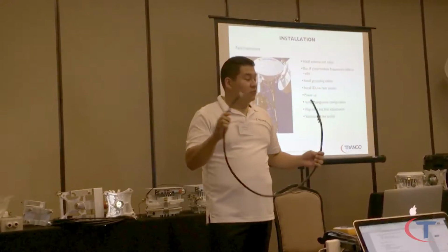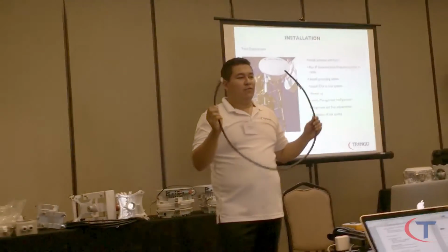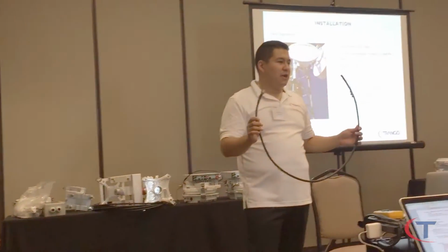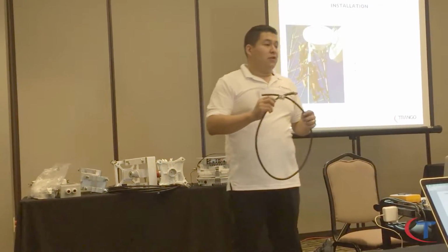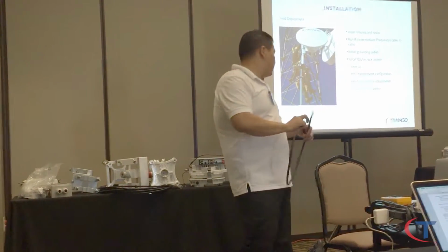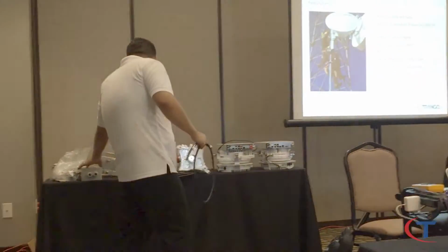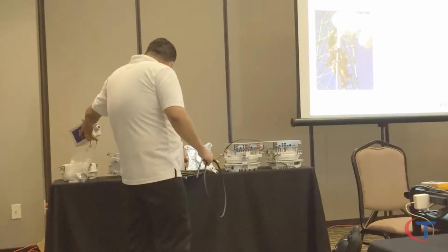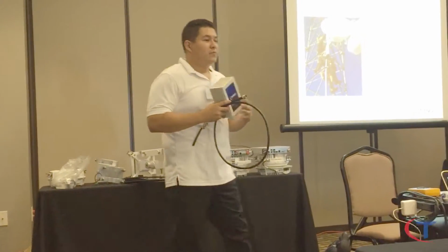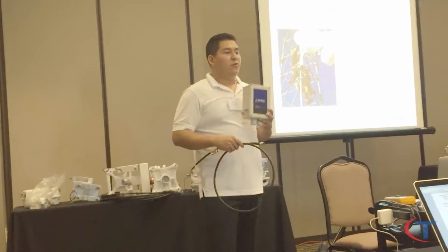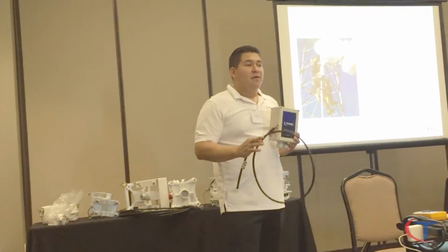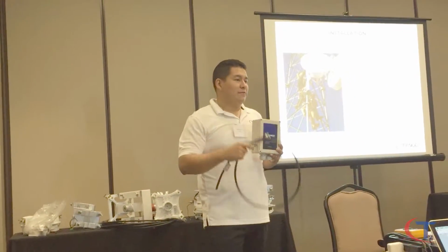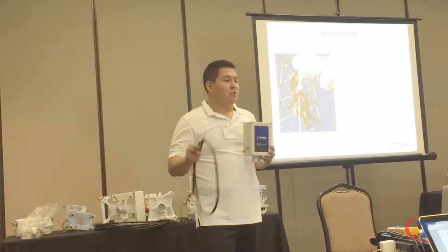Now this is designed to go 1,000 feet, so you can have your IDU well behind the actual tower with no problems for split mount systems. For the all outdoor systems, from your PoE box, it's recommended 250 feet all the way to the radio. I know standard is 300 feet for Ethernet, but the longer you go, it's a PoE device, so you are going to drop a little bit of power.